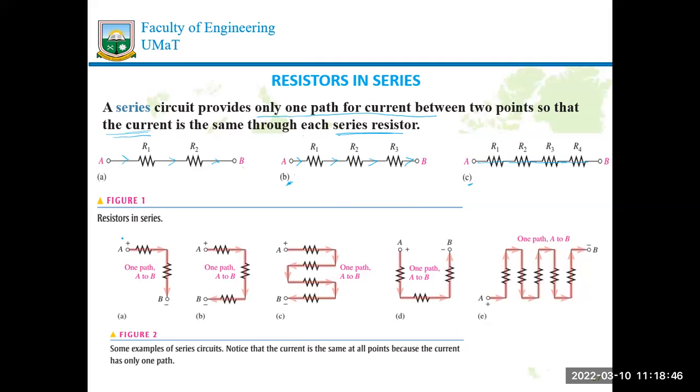Now, what we have next is just the topology that has been changed, how the alignments are. That's all that has been changed. By looking at it, you see that the same current will flow through that resistor and through that resistor, and the same through this, that, and this. If I drag point B to align with this resistor, assuming this is R1 and R2 is here, I will get the image I have up here.